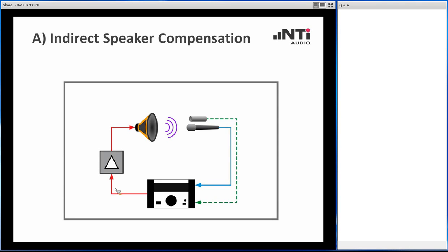It's very fast, it covers a bandwidth of interest, and it has many advantages. So we generate this test signal from the FX100, amplify it, and bring it to the reference loudspeaker. Then we have our reference microphone, which is indicated here, plus, of course, the device under test, the microphone we want to evaluate. All of that in a room.